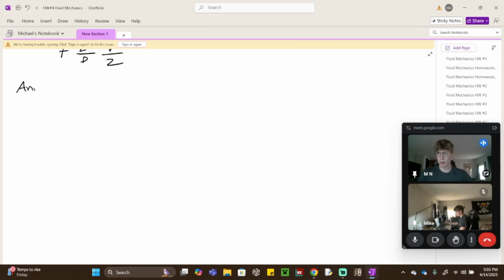Rewrite our annual cost equation that we are analyzing. So we have our annual cost equals Cc times L times D plus Pc m dot times our friction factor because of its units, which is going to be F L over D V squared over 2. And now looking at m dot,